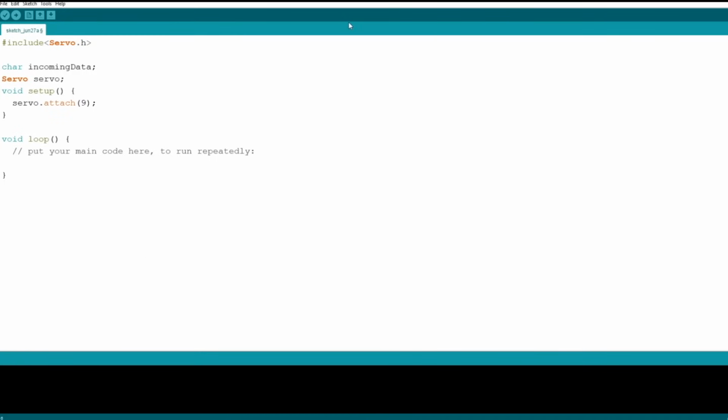So for this, let's move to a new line and call Serial.begin. As you know, we need to enter one parameter here, which is our baud rate speed. When we completed our Python code, we defined our serial port baud rate speed as 9600. So let's define 9600 here and put a semicolon. And finally, let's move to a new line.